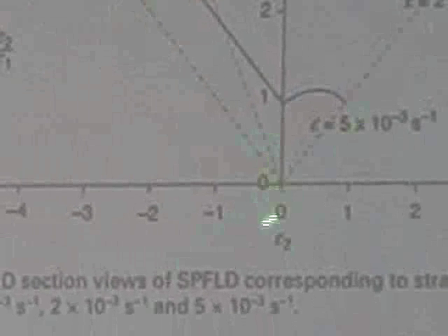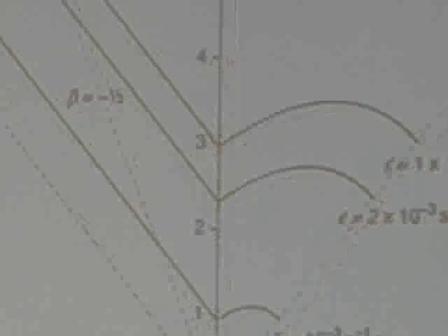For certain types of metals, when the biaxial strain in the transverse direction E2 is 0, you might have 30 or 40 or 50% elongation in a regular old tensile bar. But in a superplastic bar, you can have 100%, 250%, 300%. And in fact, when you start stretching or compressing in the transverse direction, you actually can get even more strain, and that allows you to do all kinds of sheet metal forming operations when it's superplastic, but it also helps you even when the material is not superplastic. So then to review a little bit of superplasticity.